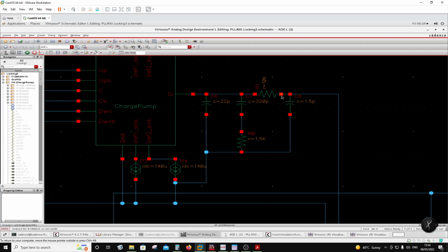Basically this RC combination R3 C3 is for reducing the ripple. Now where the ripple is coming from is basically here there is a fractional MASH sigma delta, which is being 12.5% the count of the lowest coarse count. Because of that, you are going to see fluctuations, and you can control those swings using this capacitor. Now as per the computation I'm putting the cap, but you can slightly increase this capacitor by 30% to further reduce this excursion.